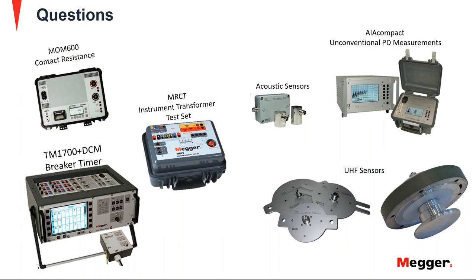I mean, the system is already online. All you have to do is take your sensor and move it to a window or a flange, and pick up PD activity. And if you don't, then you're always free to move to another window or flange. And typically, as we saw, you have multiple sensors, which is the point of this, where you can pick up a signal and then migrate more towards that area and try to identify where that defect may be within your GIS system. So definitely these can be installed in other places, though these places are limited by the application of the sensor itself.